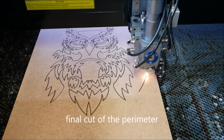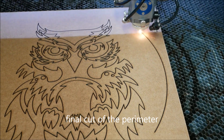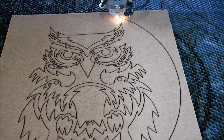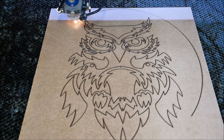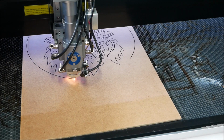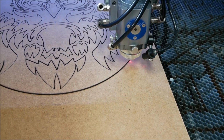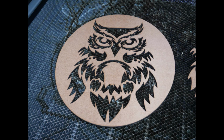Shown here is a shot of the camera I have inside the laser, which saves me opening and closing the lid. I'm using about 35 psi of air to help with the cut. That's what gives it a nice smooth cut.